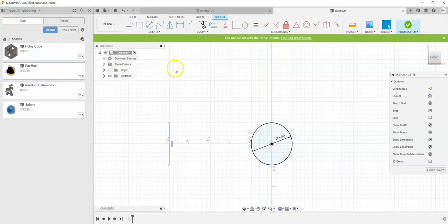But if I mess it up, so let's go ahead and hit undo, and I'm going to draw this line again. And this time I'm not going to draw it vertical and hit escape, but my line is still close to vertical. I can go to my vertical constraint and select my line and make it vertical after the fact. And I'm going to right click and hit cancel. And you'll notice this line is not fully constrained, and that makes sense. I can change its size and I can change its location. But actually I want to work backwards.